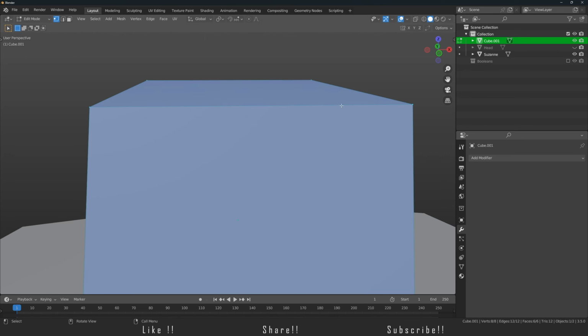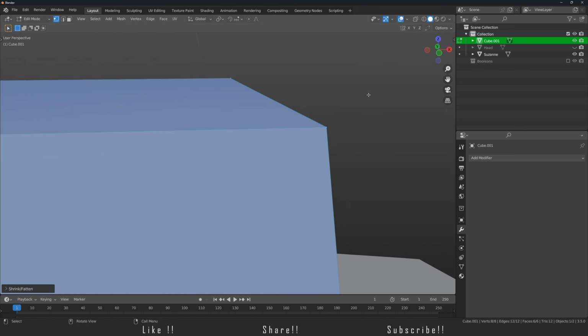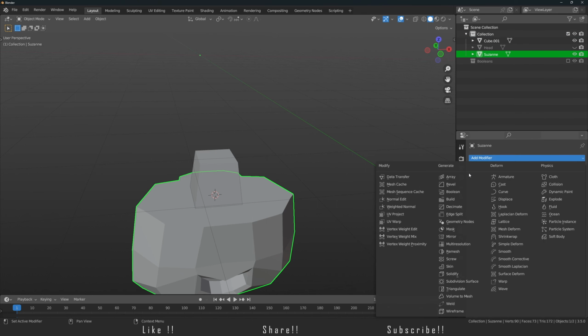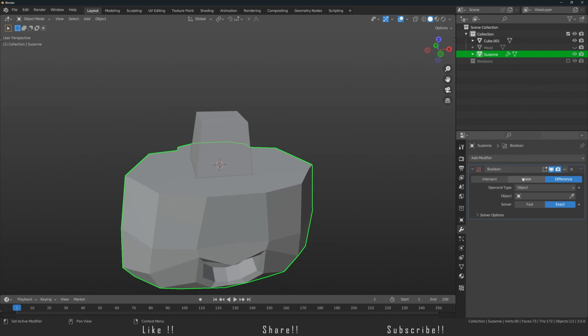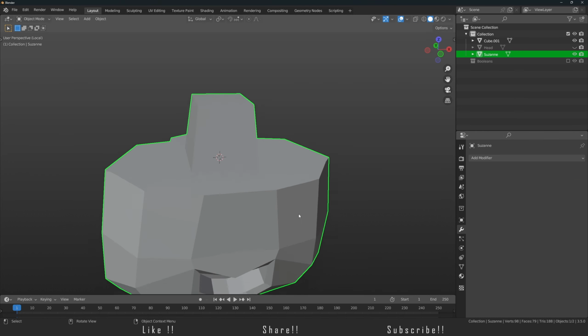I really hope that you can see how much I am shrinking it down. Let me just go closer. So shrink it down like this, and now we are good to go. So now we basically just need to boolean these together. Now I'm going to go over here to boolean, and now we're going to use the union because we want to make sure that these two are actually going to get connected. Now I'm going to select this, and yep, we basically have the male key.